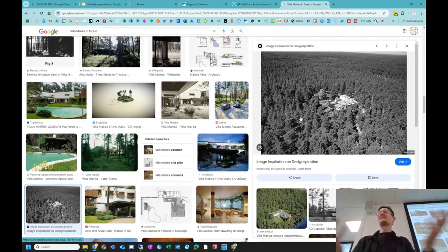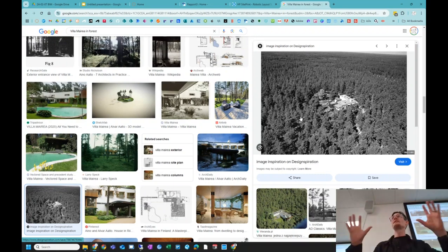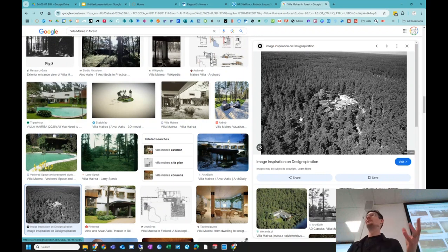Well, that's mostly the thing that trips people up: access and planning and also timescales. You need to have the design finished in order to send the design to the factory so the factory can build the thing, and they might have like 10 weeks to do it. And so you need to know before you get there that the building site's going to be ready. But if you get set back, are you just going to let the truck go with all your stuff on? Are you going to pay for it to be delivered again? That's the logistics and admin of it, and that's the thing that really kills modular construction, or can often do.